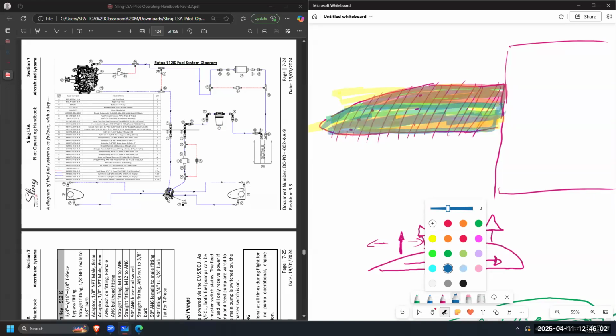So guess what? Are you going to create enough lift if you have too high of an angle of attack on this little bit of surface? That's the answer. Center of pressure equals center of lift. Center of lift moves forward with an increase in angle of attack, and the surface decreases. Surface available, surface usable, whatever you want to call it, right?